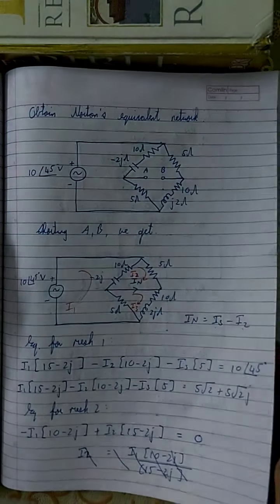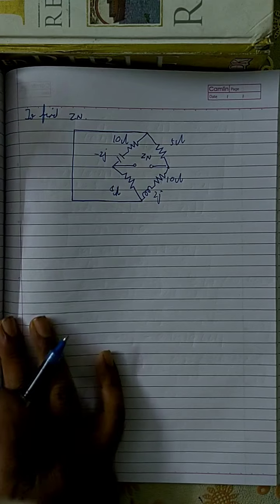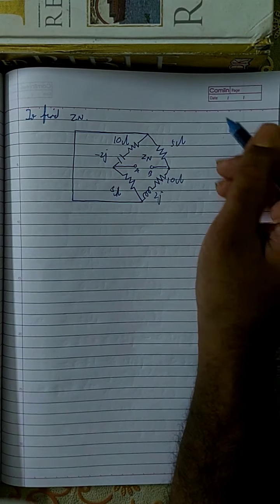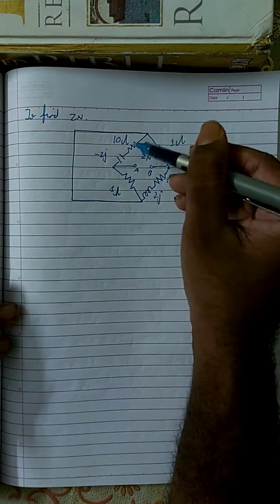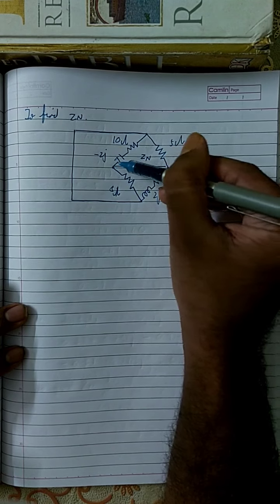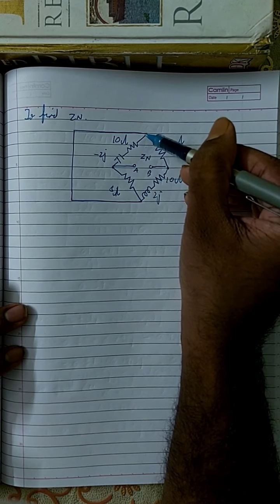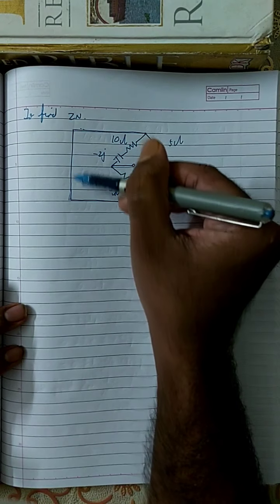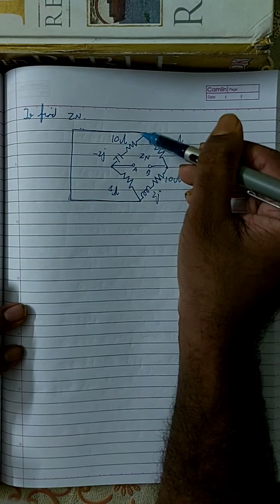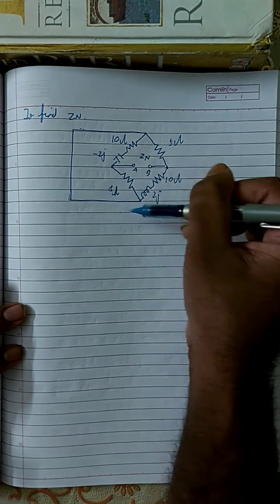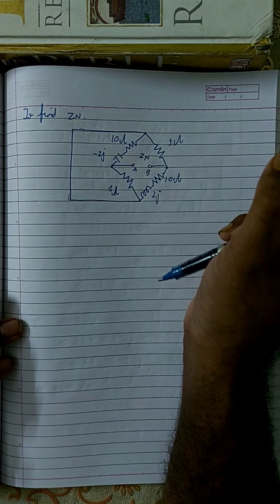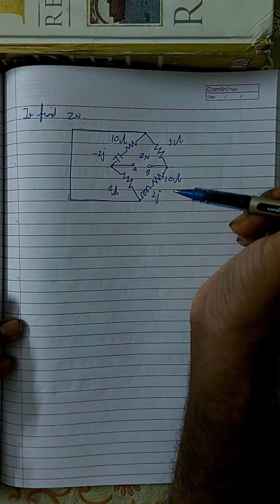Okay, all right. So now A and B. Okay, so now if you look at these two branches, this end point is the same for both the branches, and this point is also the same, because there is no element over here. So this entire connection, this horizontal line, this vertical line, and this horizontal line is actually a single connection, which means these 2 points are also the same. In other words, these 2 branches are in parallel to each other.